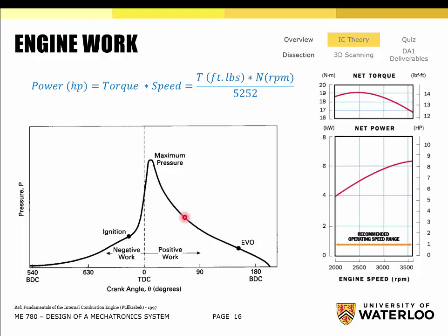Because of the way that the kinematics work out with the crank motion, you don't want it to be right after 0. You want it to be about 12 to 15 degrees after 0 because the force is not pushing directly down on it. It's pushing the crankshaft through its rotation. It's like pushing on a bike pedal. You don't want to push directly down on it. You want to push it slightly after it reaches the top. So 12 to 15 degrees is what really works for most engines. If you want a more detailed explanation on where 12 to 15 came from, I can give that to you. Anyone else? That's a great question.